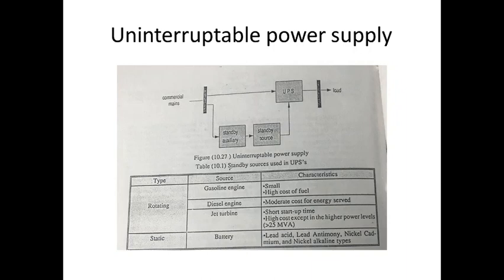Units may require special ventilation and maintenance due to battery requirements. Also, larger units may require specially placed battery rooms. Some static UPS require specially designed battery charging units. All static UPS involve the use of an inverter, and these inverters incorporate power semiconductor devices. So the main disadvantage of the static converter is the use of a battery. Batteries have limited life and energy storage capacity, and the cost and size calculated per watt-hour stored may not be competitive.